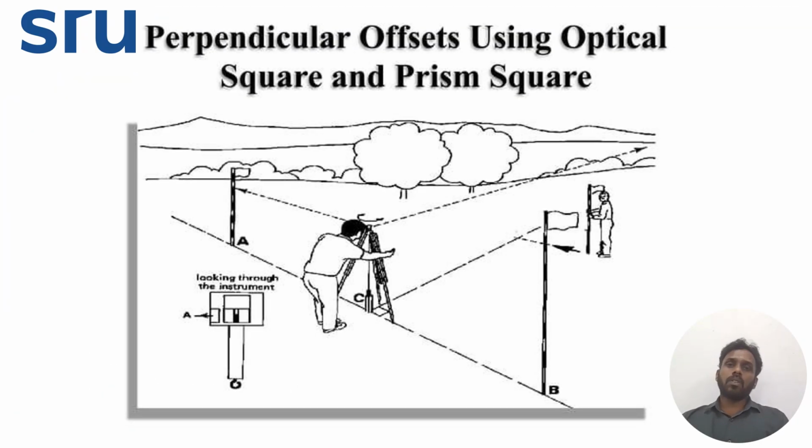So how are you going to mark a perpendicular offset using a prism square? You can see here. So this is your prism square, right? You are fixing that exactly at 90 degrees. So first you have to locate your point A and point B. You have to align your cross tab or your prism exactly looking towards your point A and point B. Then you have to go to the opposite direction.